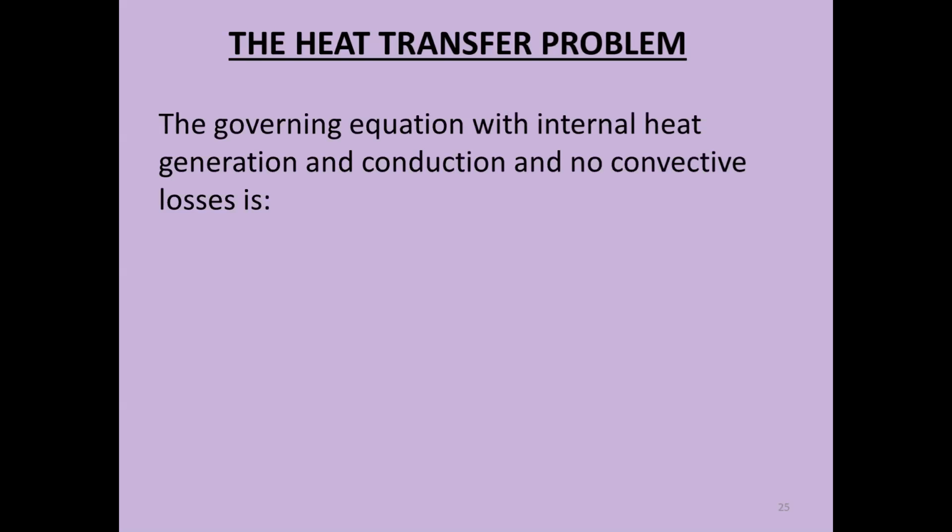Those fins obviously are air cooled, and the governing equation which is going to be used in this particular case is the equation on the display. Kindly note that this expression has a value Q on the right which represents the internal heat generation, and it also includes heat loss because of conduction, but there are no convective losses to the atmosphere.